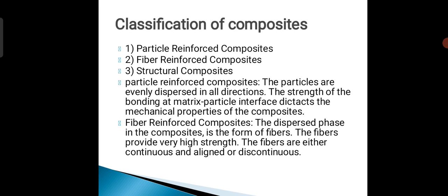Next, classification of composites. Particle reinforced composites, fiber reinforced composites, structural composites. Particle reinforced composites. The particles are evenly dispersed in all directions. The strength of the bonding at the matrix particle interface decides the mechanical property of the composites.